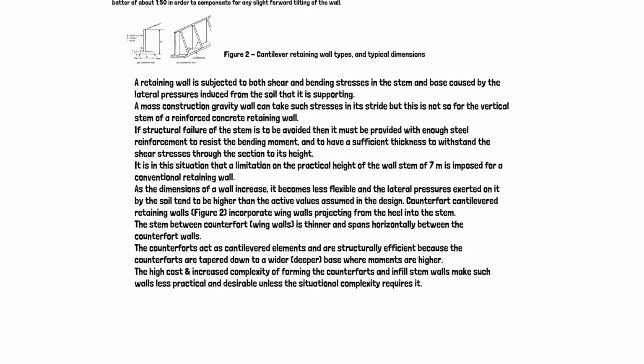A retaining wall is subjected to both shear and bending stresses in the stem and base caused by the lateral pressure induced from the soil that it is supporting.